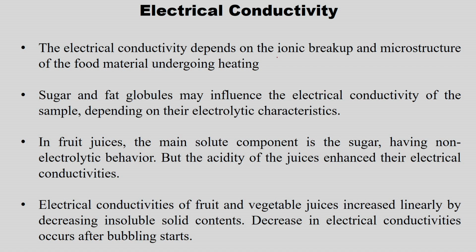So, it depends upon the ionic breakup and microstructure of the food material undergoing heating. If you remember, the current flowing through the food is nothing but a flow of charge carriers, right. So, how much current flows depends upon the ionic breakup as well as the microstructure of the food material which is undergoing heating.